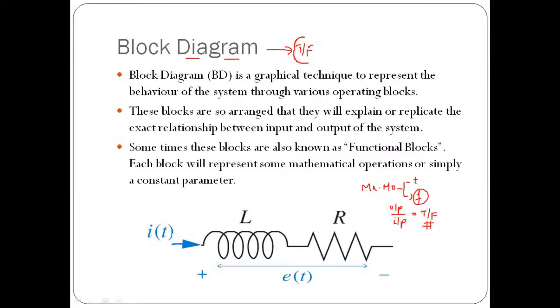And once we have the knowledge about the transfer function of the system, then it is very easy for us to determine the stability, or poles and zeros, and characteristic equation of the system. We are also in a position to define time response analysis and frequency response analysis of that system, and so on. So ultimately, in order to determine the behavior of the system, we should know the parametric function of that system, which is nothing but the transfer function. And to determine transfer functions, it may be possible that we have the representation of the system in, say, a signal flow graph or a block diagram.